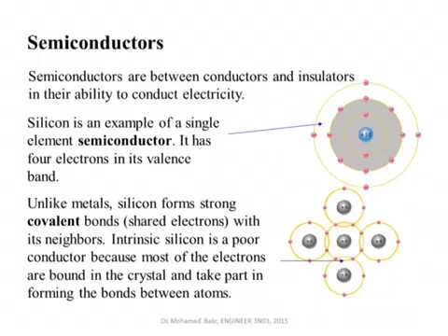And at room temperature, they do not conduct current. If you heat them, some of these covalent bonds can be broken, and these electrons become free, and then they start to conduct current. And I will show you later that another way to increase the conductivity, or increase the number of electrons available for conduction, is by adding impurities. And we'll talk about that in 2 weeks from now when we get to start the p-n junction part.